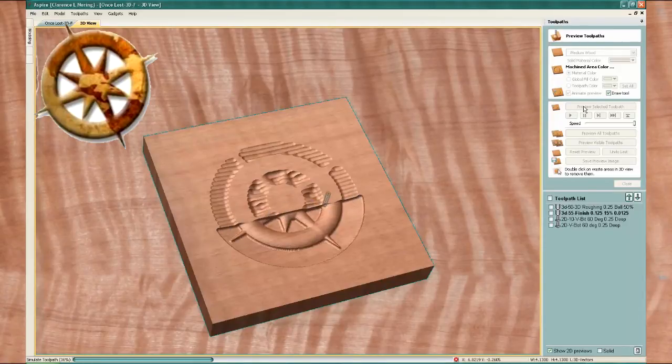Now right around the edge of the circles you can see the individual tool lines. If we did a circle type carving, they would be gone, but you'd end up with hairs just about on every edge. So it's kind of a give and take. It is possible to run another toolpath where it does a circular toolpath around the edges of the circle. You would end up with a much smoother cut. You wouldn't see the individual toolpath.